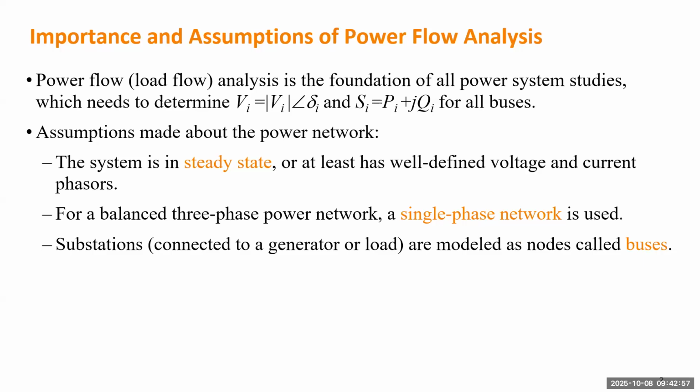How do we model substations? If you have the opportunity to visit any substation, you will be able to see some layouts. The layout just shows how the line is connected to the substation, which direction it will be coming from, and which circuit breaker it will connect to. On the power network, a substation is just a single node. But actually, it's another whole system. It can be very complex. They can have tens of circuit breakers, separating line by line, equipment by equipment.